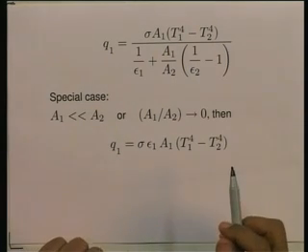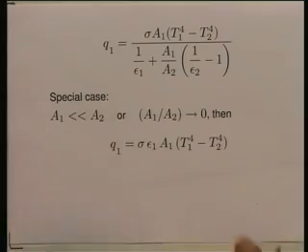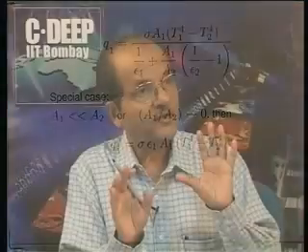Keep that in mind. So, now we have derived a general expression for a variety of geometries, though we started off only with the case of the annular space between two tubes. We extended it to the annular space between two spheres. We said the spheres could be eccentric, the tubes could be eccentric, and then we said in fact it could be applied to any situation where one object completely surrounds another.